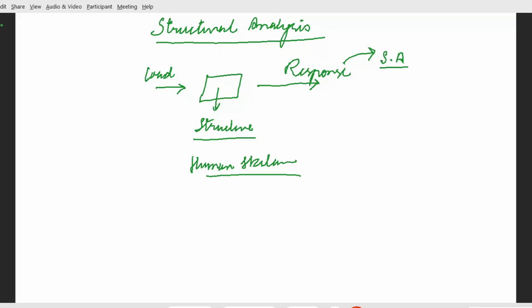And analyzing does not only mean that you calculate the shear force and bending moment diagram. You often have to see whether the structure is stable or unstable, and what parameters we need to see before designing any structure. We have a number of parameters. We have to see the zone in which we belong, for example zone 5 of the seismic map. It's a highly seismic prone area, and for such regions, what are the necessary steps we should take in order to construct our buildings in zone 5? Then we have environmental conditions as well, right?